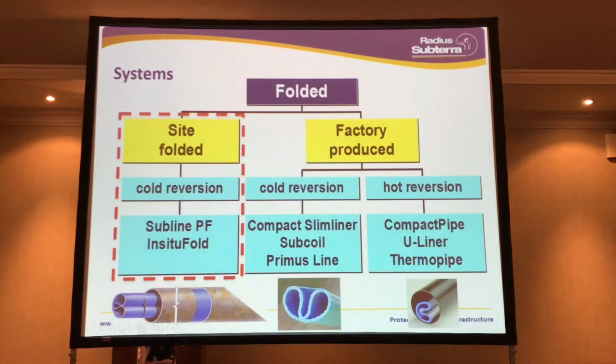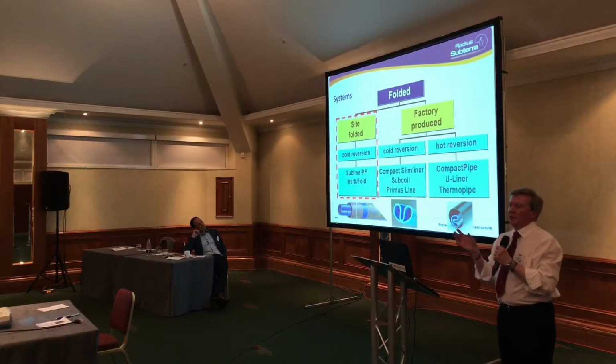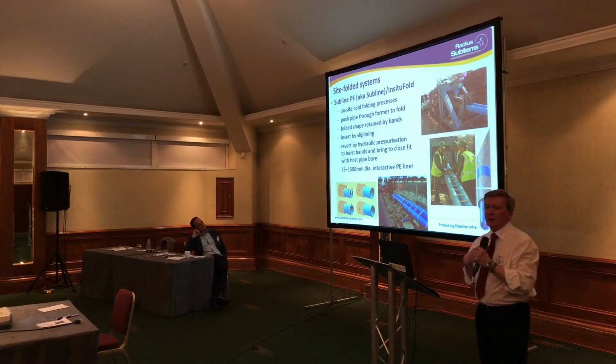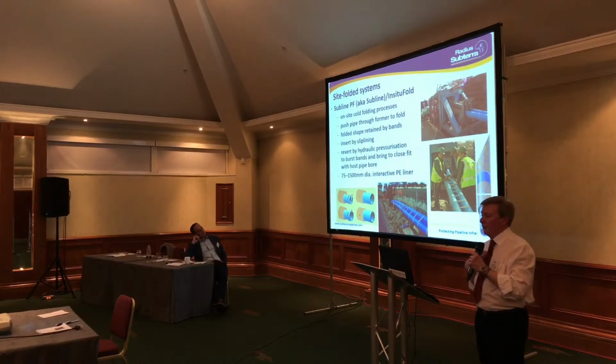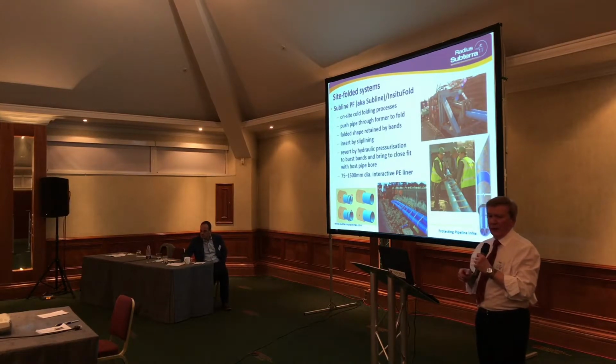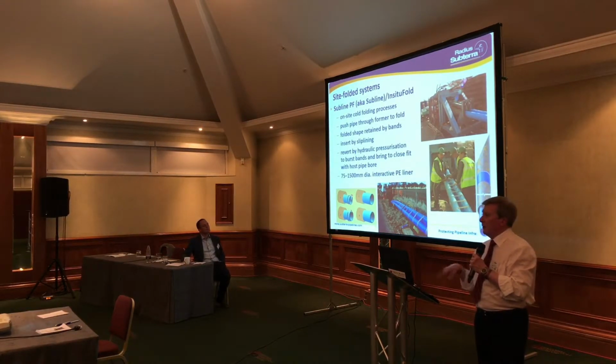Again, it's really naming of parts, so what technologies have been available are used. There's the site-folded systems. This is the one that I'm most familiar with because that's Subterra's offering throughout over the last 20 years or more. It's an on-site cold folding process using thin wall liner pipe. I've said all that before.